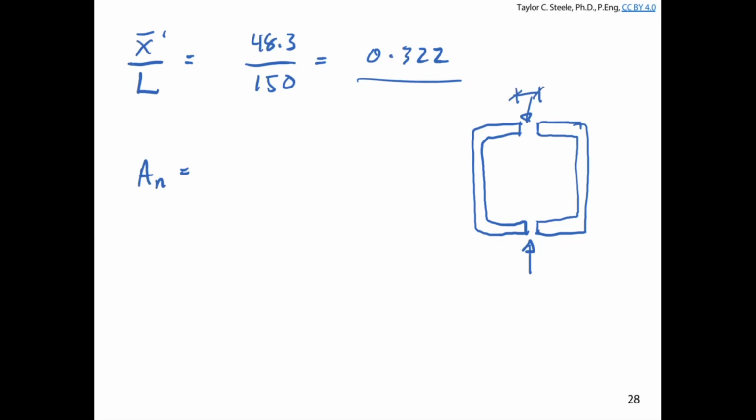If you were building this and you were cutting out a hole in the HSS to slot over the gusset plate, how wide would you make that cutout, do you think? Maybe the thickness of the plate plus a little bit of tolerance, right, to make sure it fits over. So we're going to make this slot the thickness of the plate plus 2 millimeters, just to make sure it fits over the plate. It's not going to be perfect, so we need to make sure we can fit that up in the field. And so we're going to have this on two sides.